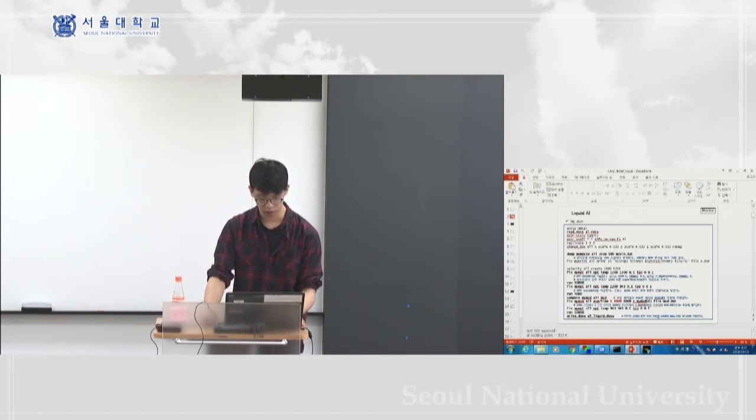So here it is the NPT command. The former part of the command is the same as the NVT command. Here we set up the temperature first, and the first one is the starting temperature, which is 1200 Kelvin, and the second number is the end temperature, which is the same as the starting temperature, and this number is the damping constant of temperature.